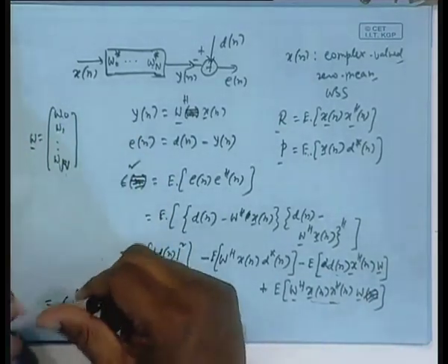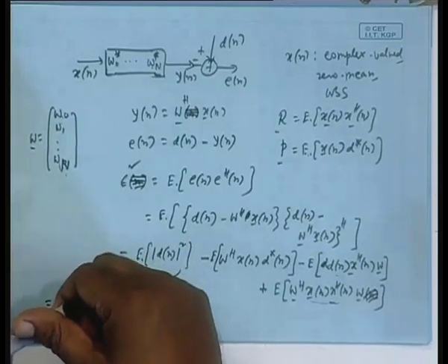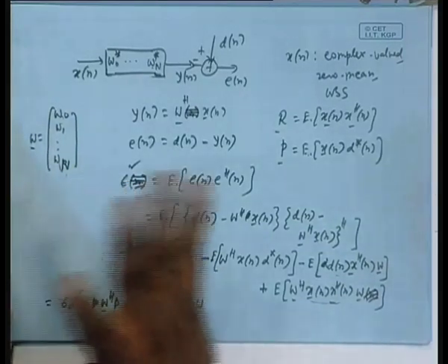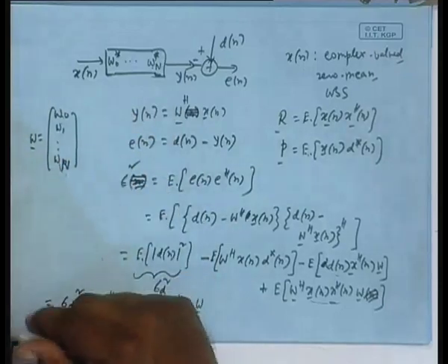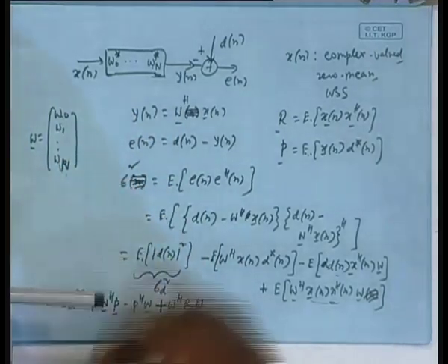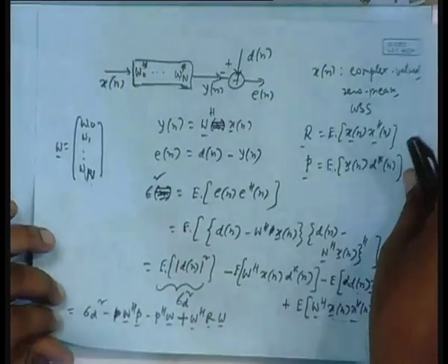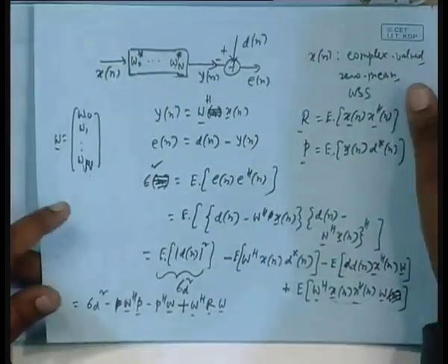So that symbol is a complex symbol. When you transmit, basically you transmit one waveform, but when you recover the signal out of it, there are two components, and they are treated in the complex variable way, I and J. So if you want to develop an equalizer, you have a complex equalizer, which will be like this. Complex cases are our construction for our convenience.